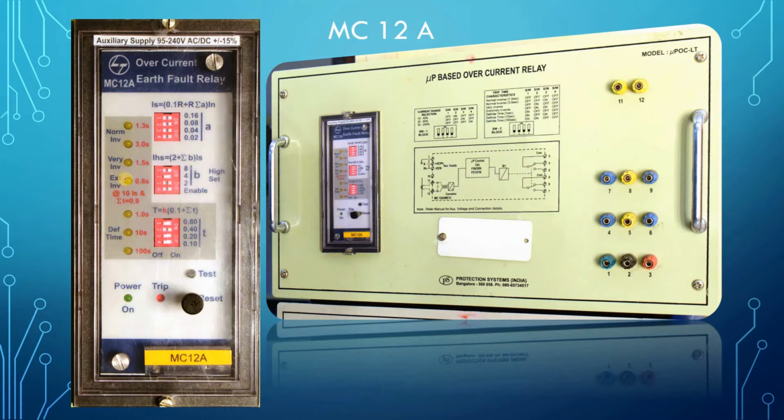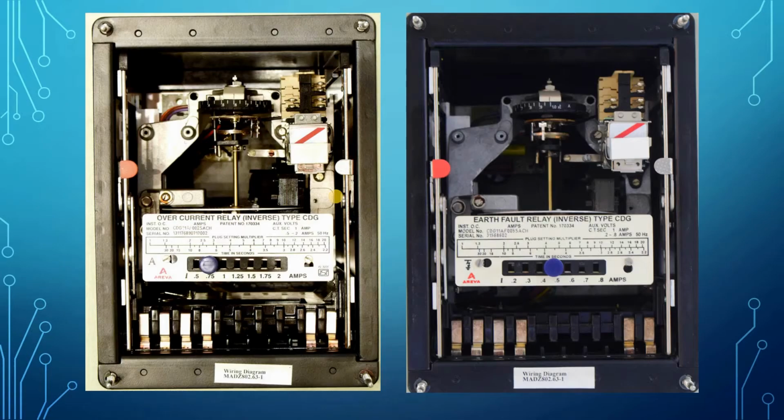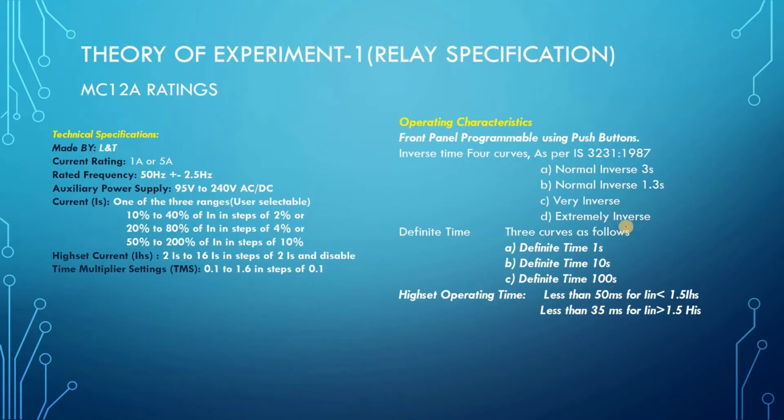That is nothing but the extreme inverse characteristic. Similarly, definite time 1 second, definite time 10 second, definite time 100 second. But this 100 second also can be manipulated with the help of TMS. If TMS is 0.5, then the time will be 50 second. If TMS is 0.1, time will be 10 second. Depending on the value of TMS, we can set the definite time at 100 or below 100, or in between. But time should be fixed in case of definite time characteristic.